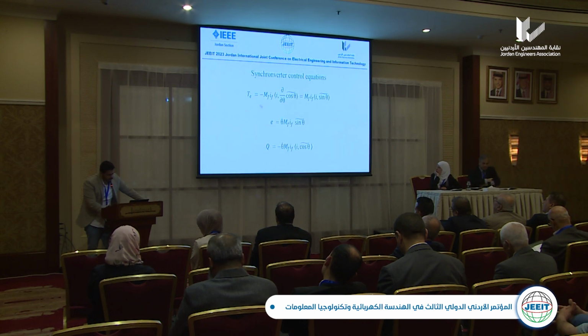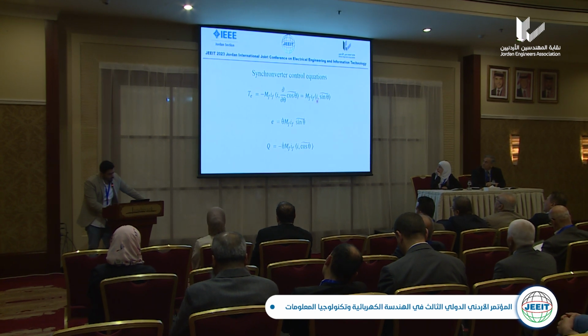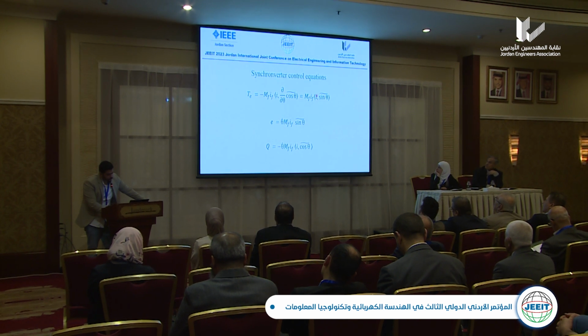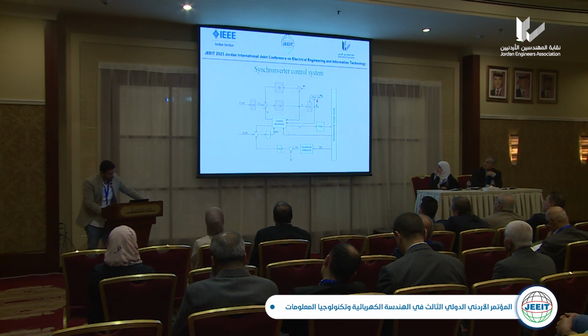In this equation, the electrical torque equals minus MfIf multiplied by the vector dot product between i, the three-phase current, and the sine tilde of theta.